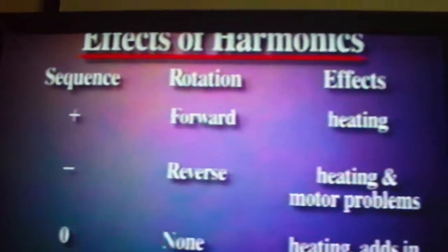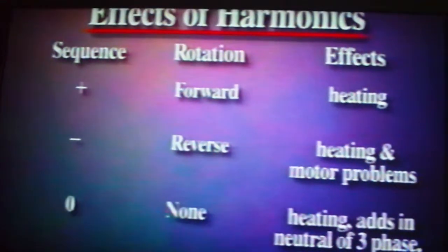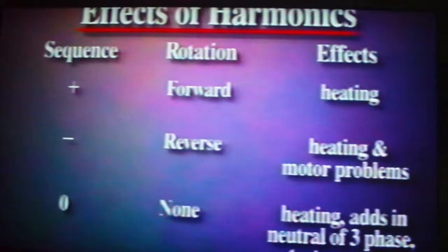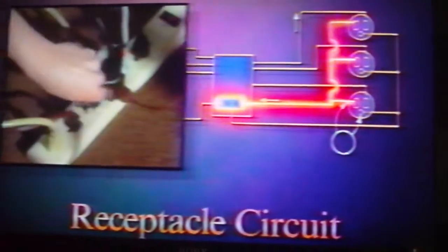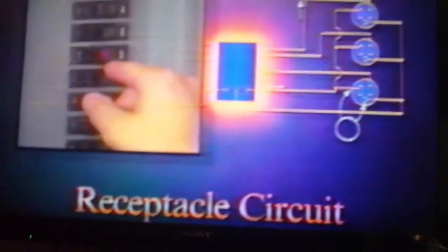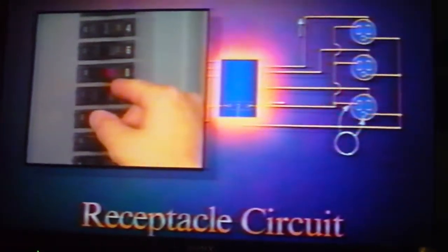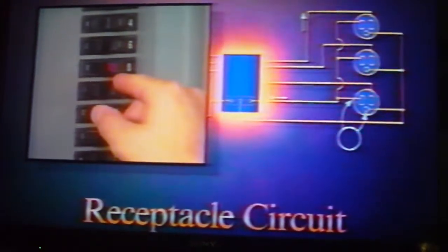The effects of harmonics show up in the power distribution equipment that serves both the single-phase and three-phase nonlinear loads. Single-phase nonlinear loads are typically 120-volt receptacle and lighting loads found in offices and commercial buildings, while three-phase nonlinear loads are usually found in industrial plants where there are large motors with adjustable speed drives. Harmonics from single-phase nonlinear loads enter the system through receptacles and then cause heating in phase and neutral conductors and bus bars. At the load center, harmonics can cause premature circuit breaker tripping due to heat and frequencies greater than the 60 Hz rating.